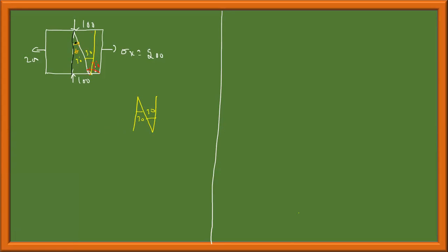Top down, sweep the clock. I am coming from the top, I am sweeping the clock. Since my sweeping is in anti-clockwise direction, my theta is equal to 30 degree, counterclockwise positive. I cannot clearly write the sketch. He has given this angle with respect to vertical, not with respect to horizontal. That he has to explicitly give, but unfortunately, he has not given like that. With respect to vertical is 30 degree.